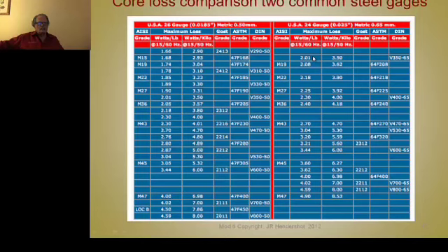That's a big difference. And as you can see, the same thing if you go up to real low cost materials, like these up in here. These materials are the ones used in your refrigerator and ceiling fan motors and things like that. They have twice the core losses of these steels here. Then the M15 is the lowest of the silicons. Then you have to go to Carpenter 49, or the other trade name, Hyperco 50. Hyperco 50 will have core losses of half of these again.